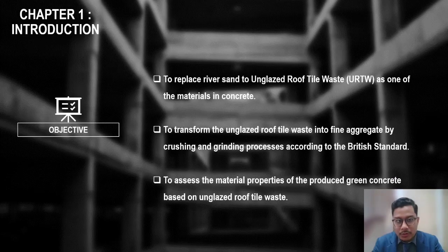Based on the background and problem statement that I have mentioned before, I have come up with a few objectives. The first objective is to replace river sand with URTW as one of the materials in concrete. Second, to transform the URTW into fine aggregate by crushing and grinding process according to the British standard. And third, to assess the material properties of the produced green concrete based on URTW.